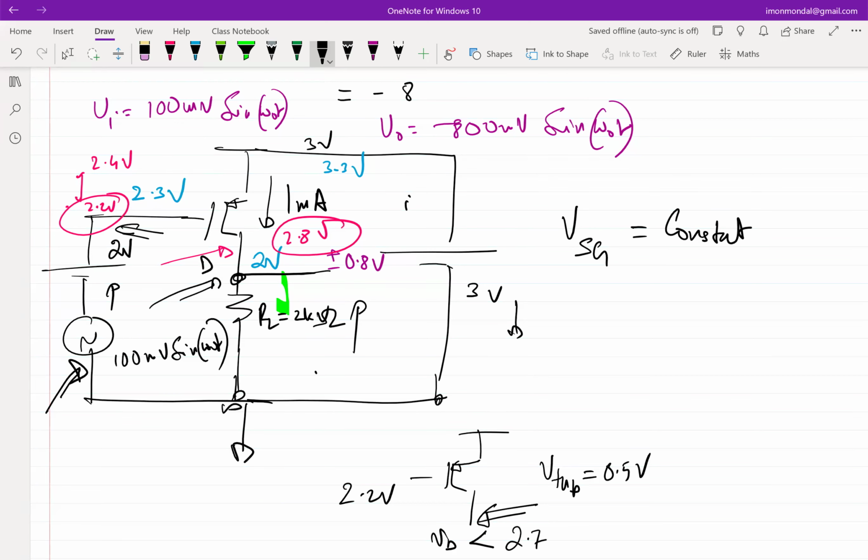So we can play the same game, right? We increased both the gate and the source voltages by 300 millivolts. I'll increase by 400 millivolts, right? So that's fine. I increase by 400 millivolts and all specs seem to be satisfied. Okay, but you see, there is an issue. This is not an issue in this case. In general, the issue is if you have to get the gain and also accommodate enough swing, you need a battery voltage which is high enough.